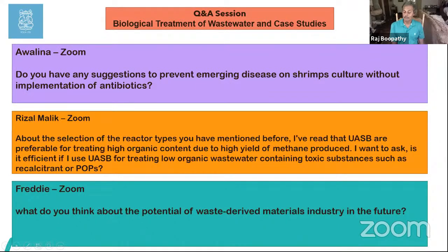Most of the Asian countries now deal with old computer parts, and they try to get stuff out, and then they wash the boards and generate wastewater. Especially in India, they are doing it, and they have some problems. Most of the time, it's not much carbon, but there are actual chemicals in the circuit board itself. That's what they're trying to deal with. So in that case, you add carbon to grow bacteria, because the chemical itself is not going to act as a growth substrate for microorganisms. So you need to add some simple carbon and then expose the bacteria to whatever chemical is in that waste, and hopefully they will remove that.